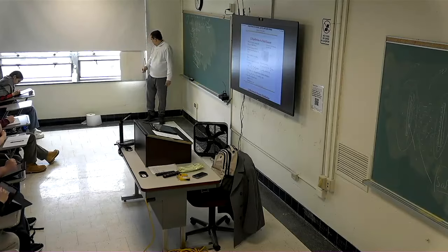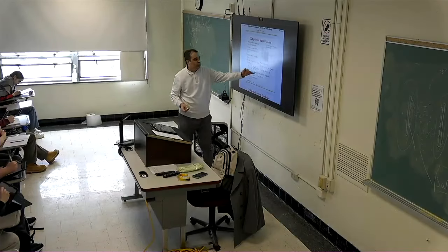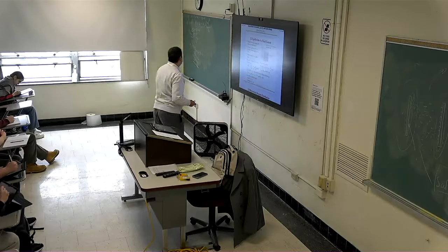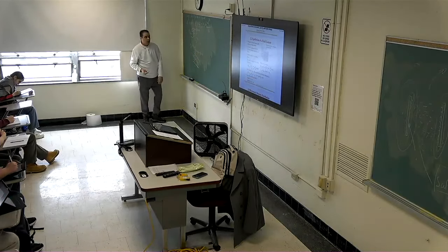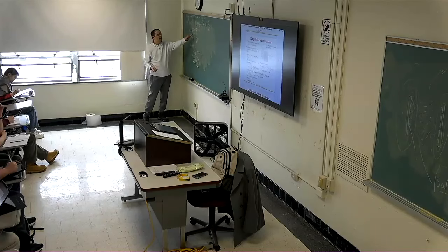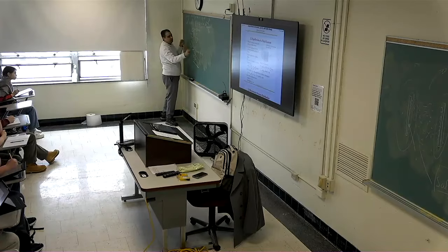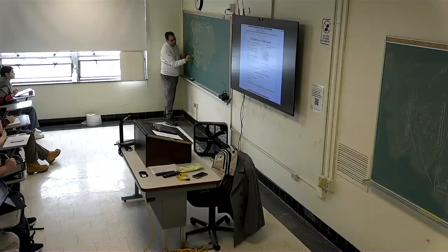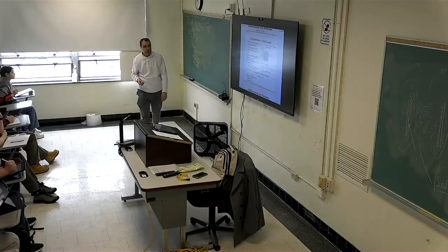So the force is partial P partial x, dx dy dz. Pay attention, it is in the negative direction because the positive direction is this way. I should put a negative sign for the first one and a positive for the second one, so the result will be negative: minus partial P partial x dx dy dz.